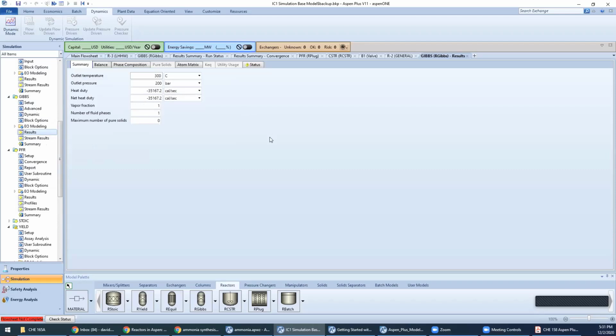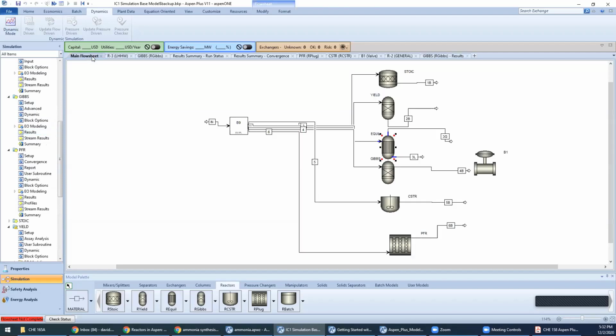Okay, and then also, hypothetically speaking, if we have a memo due that requires material balances, would it be fine to use the first couple reactors because they do balance the mass and the moles going into it? Yes. Yeah, you can use Stoic or these other ones in order to complete that balance.